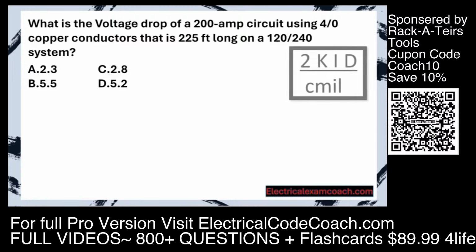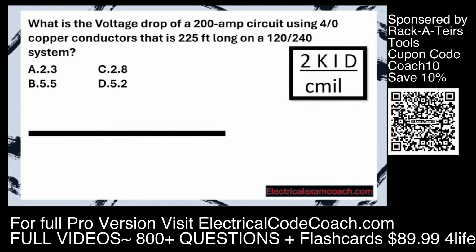Step 1, we're going to write down our formula. I like to physically write it down on a piece of paper so I can go through one step at a time. Then I'm going to draw a large division line so I can put my inputs that need to be on top and then go look for my CMILs. Let's start with 2. Is this a single phase or a 3-phase service? Well, this one is single phase, so it is going to be 2.